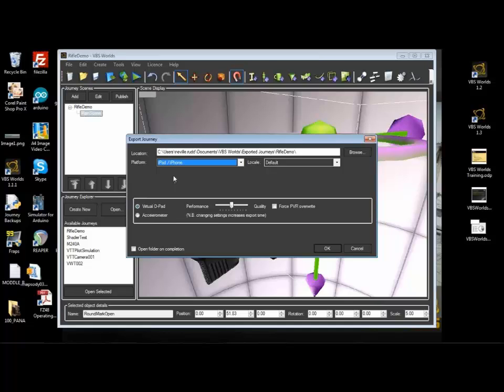Now, all of the mobile publishing and exporting options have a sort of flavour and theme. The first one is common to all of them. This is a training sim, so we actually haven't got first or third person camera on. When you have a sim that uses first or third person and your learners are moving through the 3D environment, they can either move using a virtual D-pad which appears in the bottom left of the screen. It's a thumb pad. They can move forward, back, run, and turn left and right. Or you can use the accelerometer where you physically manipulate the mobile device to move them.